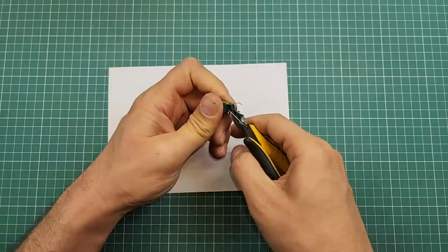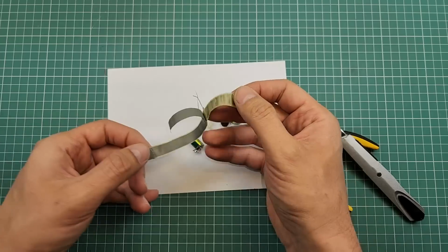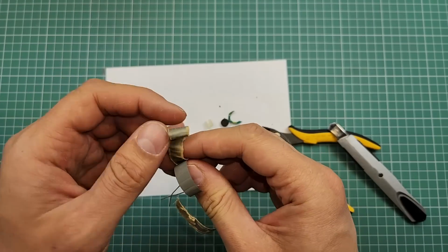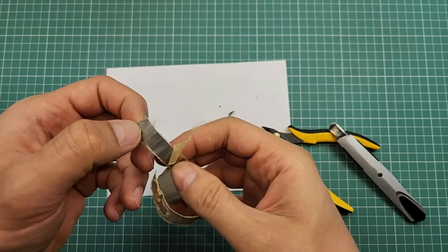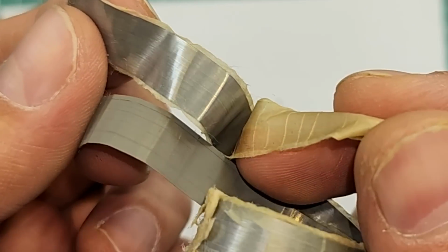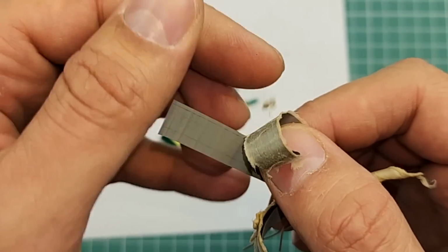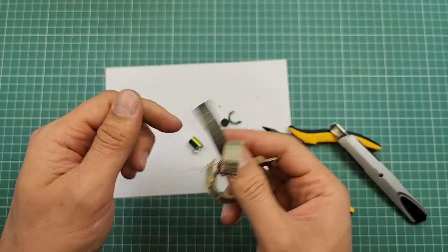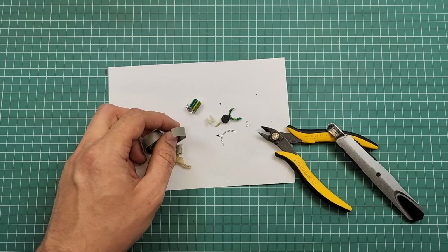Let's look more closely at electrolytic capacitors to find out where these features come from. I'm going to take apart this capacitor. Look, there are two metal plates inside the capacitor and a dielectric is separating the plates. The dielectric is impregnated with oil or something. There is nothing so special so far, but if you look attentively, you can see that these plates are covered with a thin layer of oxide, and this fact makes the electrolytic capacitors so special, makes them have high capacitance and also makes them polarized.